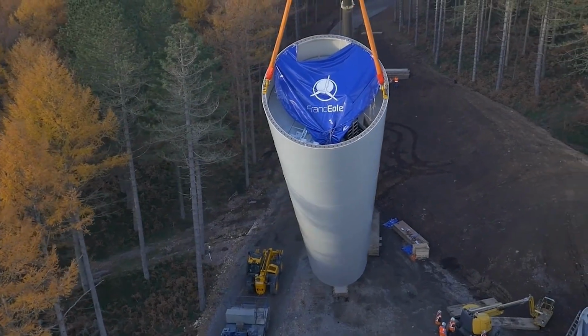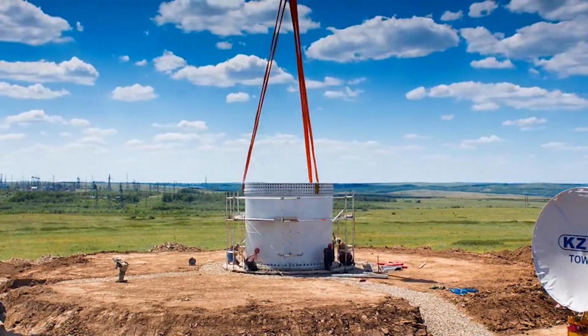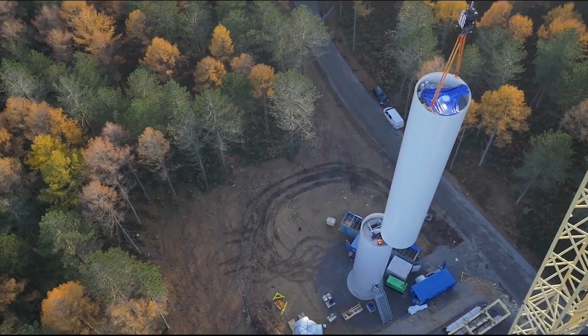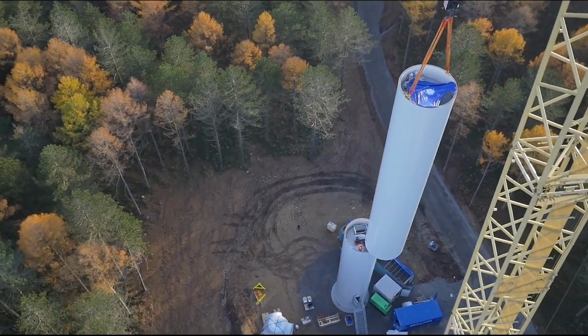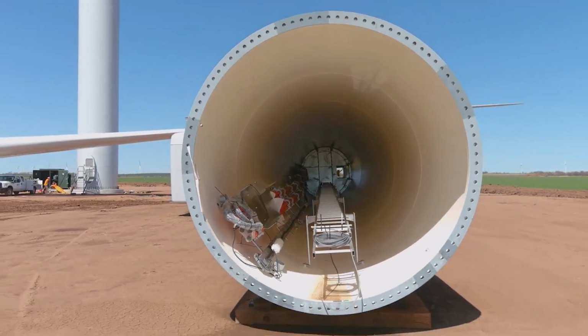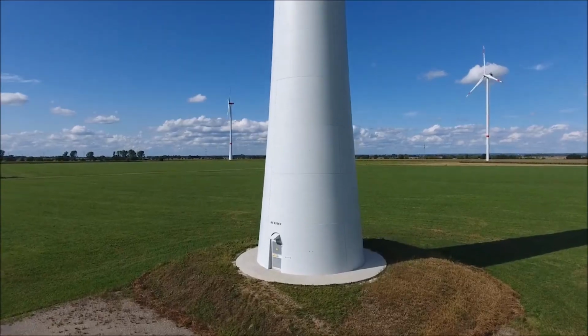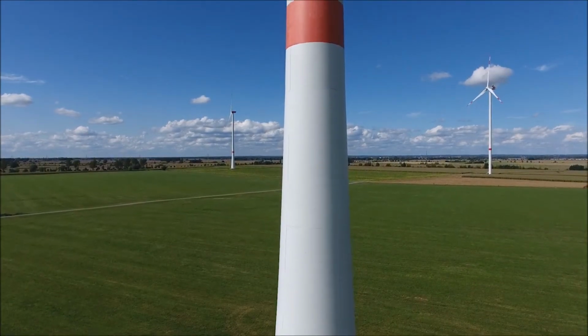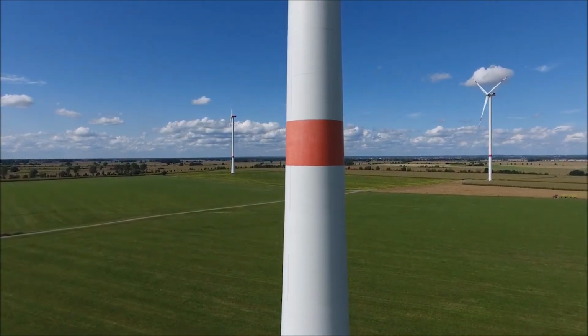Wind turbine towers are made from steel or concrete. Steel towers are the most used type in the world. They are made in sections that are connected with wind tower flanges. All steel towers are in taper shape, meaning the diameter of each section decreases as the tower height increases. Because of their closed structure, the internal parts are well protected from the elements.